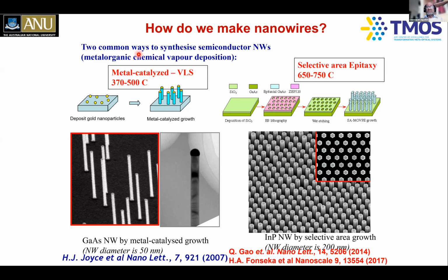We also use something called MOCVD, metal organic chemical vapor deposition. There's also an alternative technique called molecular beam epitaxy. You can use either of the techniques to make the nanowires, and it's a choice of yours, but MOCVD is widely used in the industry. For example, nowadays MOCVD reactors are used to make large numbers of solar cells, LEDs or lasers, any optoelectronic devices, including III-V solar cells as well. That's why we have chosen the MOCVD technique, to cover a broad spectrum of III-V semiconductors.